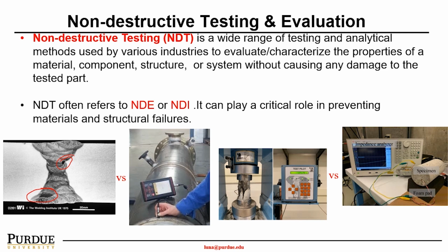That's one example. Another example is when we try to understand the strength or mechanical properties of concrete or steel, we typically do destructive testing to break the test sample. On the other hand, we could use sensing methods that send a wave to determine the resonant frequency of the material, and from that we can understand the mechanical properties, which we will talk about in more depth in the next couple of classes.